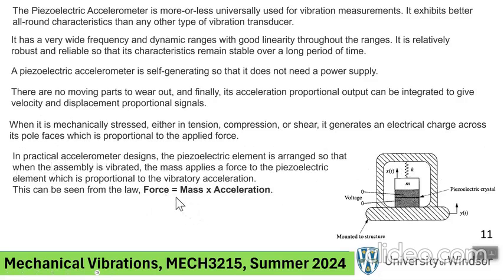Now, essentially the voltage developed by this piezo ceramic is proportional to the force that's applied to it to squish it, and we know that force is the mass times acceleration of this little m block. So you're squishing this piezo with a force F. That force F comes from the vibration of the mass.